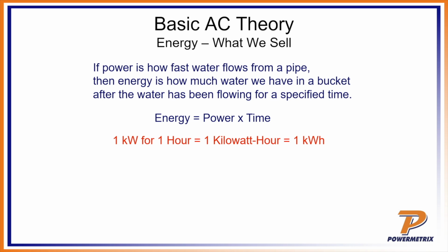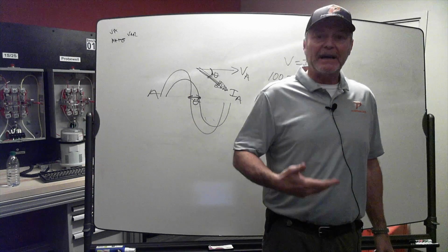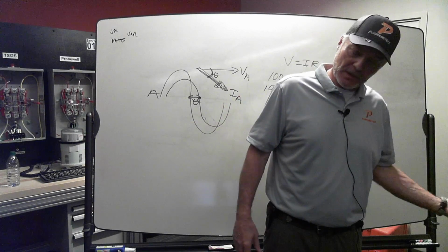Now, let's talk about the difference between energy and power. The difference between energy and power is, here in Tennessee, you get paid by your energy, but we acquire power from our dams and from TVA around here, okay? So we get our power from TVA, but we bill the customers a bill on energy, because time is involved now. I kind of mentioned it before and hinted a little bit. It's kilowatt hours on your bill, right? Not just kilowatts. There's the time component in there. And that's what we get billed on. That's what we bill our customers on also.